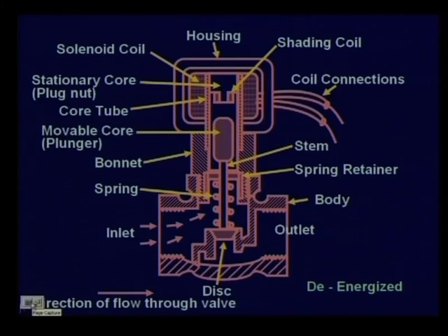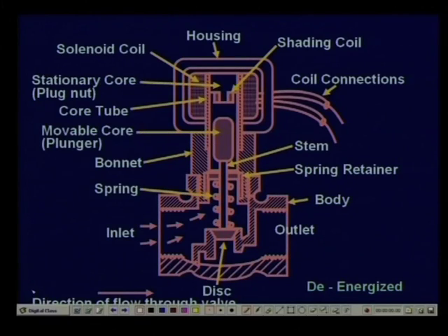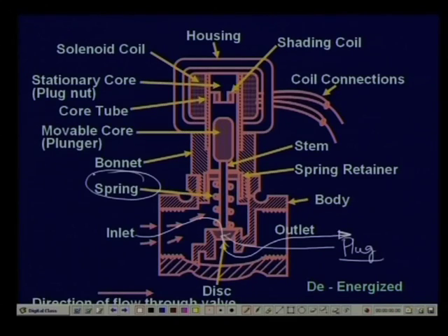So, what I was saying is that in the electrohydraulic valve pilot stages, solenoid valves are used, and this is a particular construction of the solenoid valve. You see that this is the valve, this is the plug, and this is the closed position shown. This is the inlet, and the fluid flows through this. There is a spring loading.